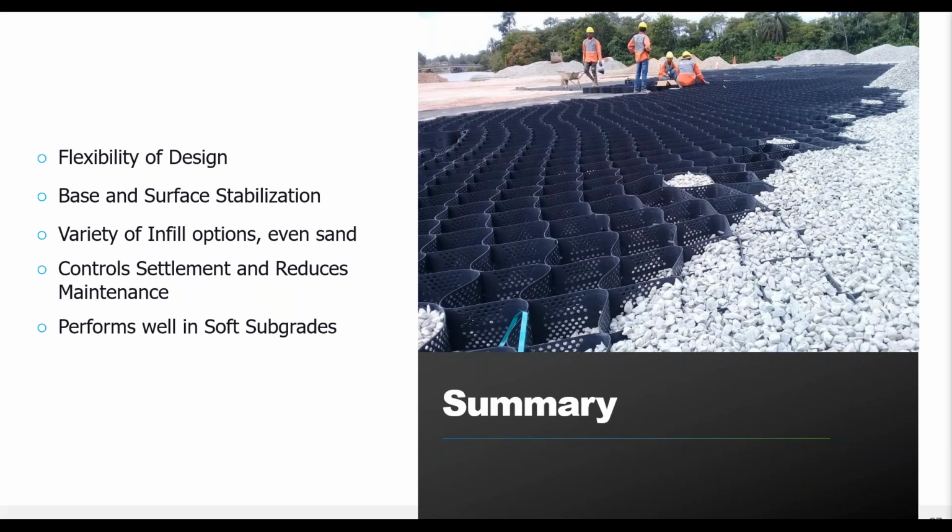So in summary, the GeoWeb load support system can be added to projects to provide a more stable and durable surface course for unpaved areas, reducing your maintenance and repairs. And then for paved surfaces such as asphalt, reinforced concrete, and roller compacted concrete, the GeoWeb system can reduce the pressure on the subgrade to reduce differential and long-term settlement to extend the lifetime of your pavement. The ability to use those low quality aggregates and sandy materials can save a significant amount of money and time. And additionally, the ability to reduce the stress on the subgrade can reduce the final thickness of your pavement.